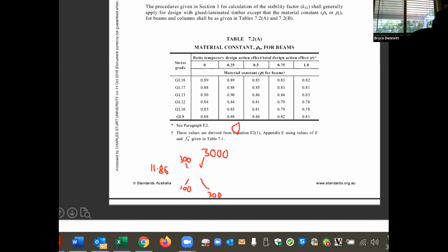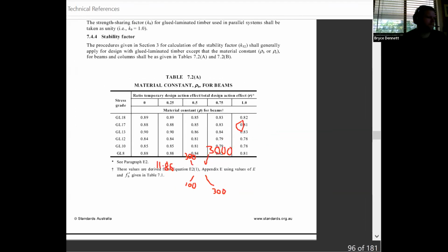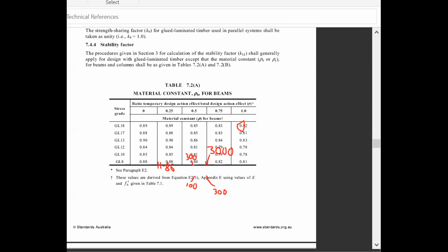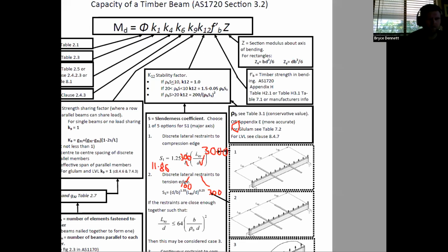Beam is a primary member. Commercial building structure. Mainly self-weight. So it'd be permanent load? Considered permanent, yep. So we use the ratios. You want to be using 0.82, that value there. Is that right? Yeah, so the structure carries mainly self-weight, thus all load can be considered permanent.